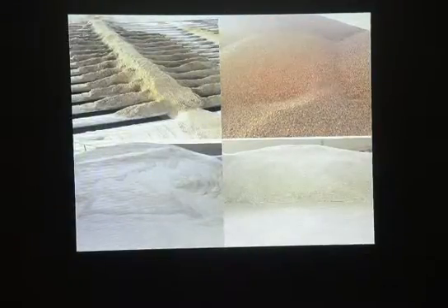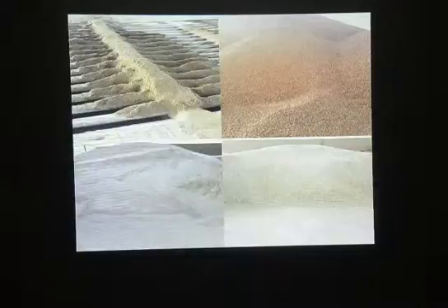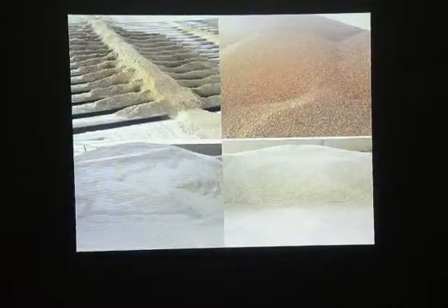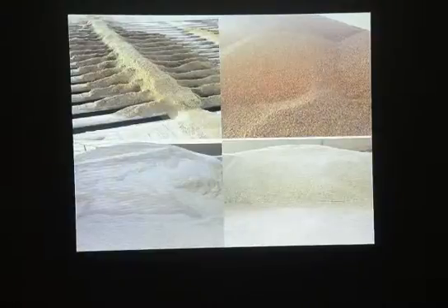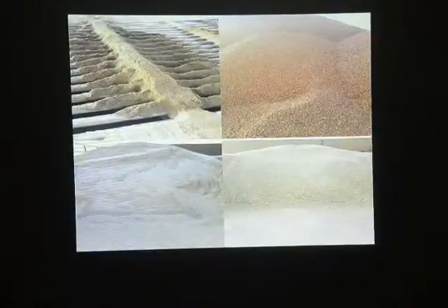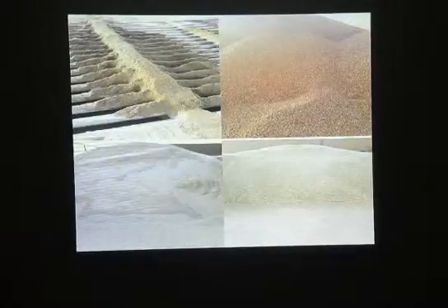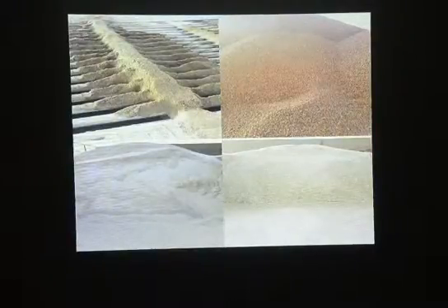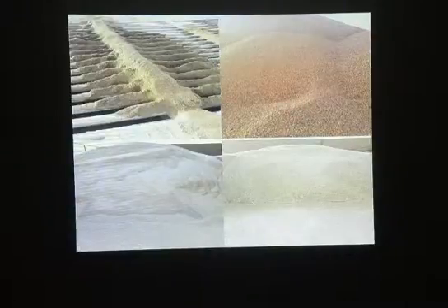And the same question, when you're talking about the percentage of the mixture, for example, 10% of the red aggregate, we are talking about 10% of the weight, not the volume. Right. So it really doesn't matter if the aggregate is larger or smaller size, because it doesn't matter if it's one big chunk or little pieces. So it shouldn't have any effect on the total weight of the block. That's my observation.